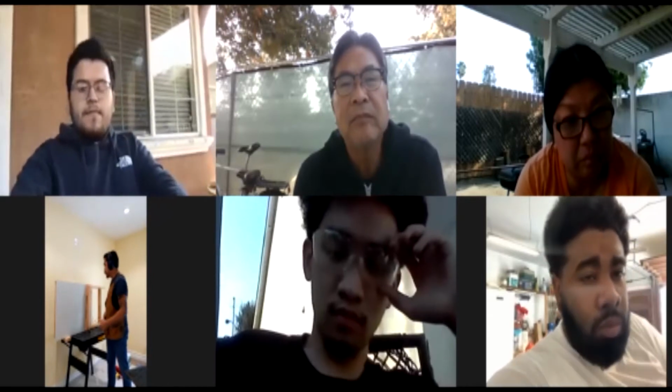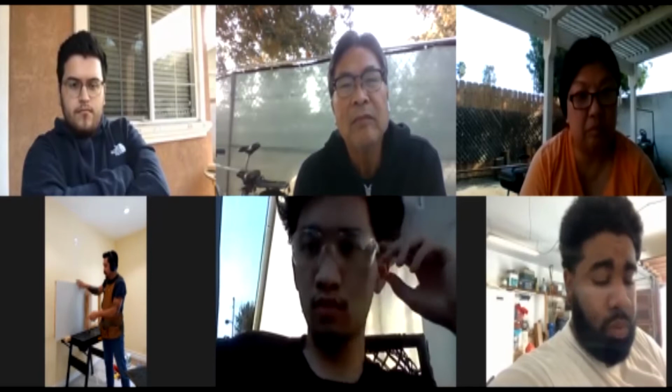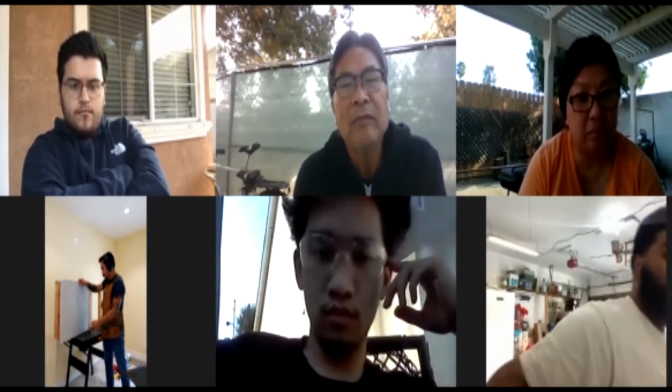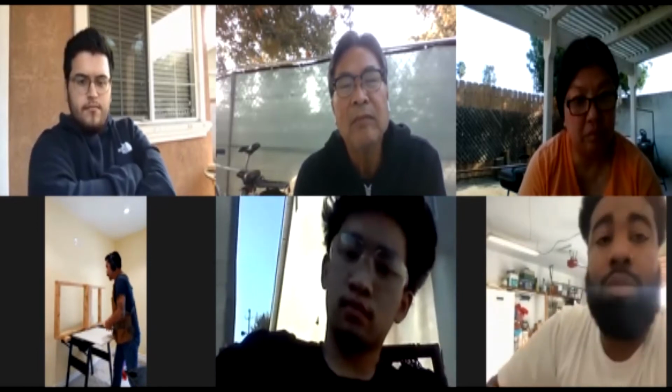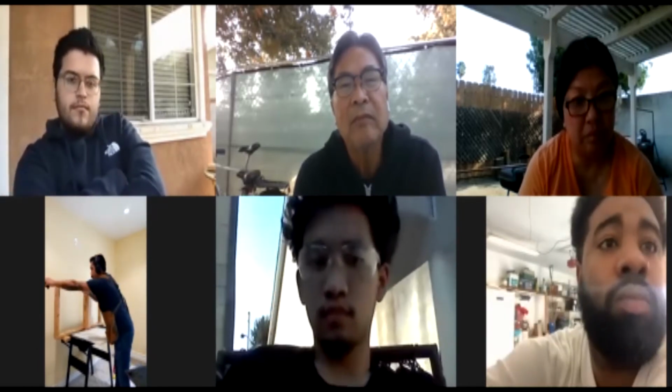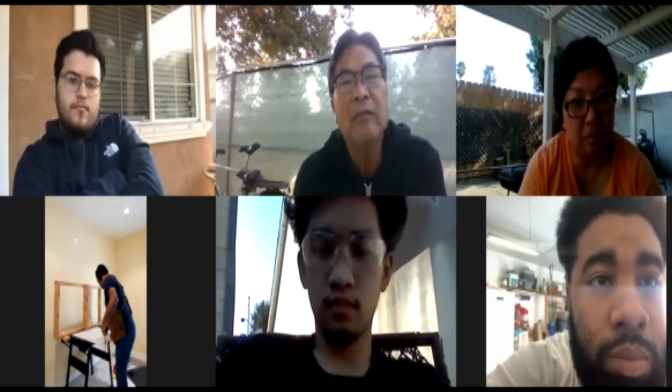I have to cut. So there are two ways that I can cut sheetrock. Measuring my space, transferring that measurement onto the sheet, right? I'll actually do that right now. So let's measure that. From here to here is 22 1/4.